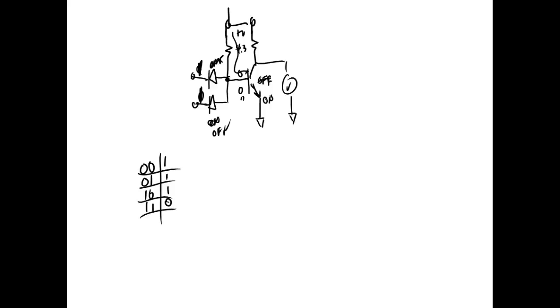This is no longer an AND gate, because the AND gate, we said, takes all highs to get a high. This would be a type of gate called a NAND gate. The N means it's got a low active output. And what we say about this is all highs equal a low.